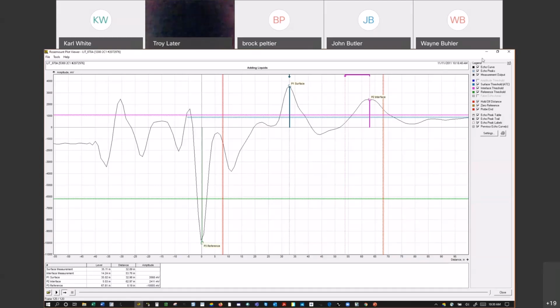Well, yeah, and even just from the operator's description where he says, I've got good interface, and all of a sudden it's just gone. I'm like, okay, well, you're going below the threshold. So before we even started this plot, I went in and lowered the interface threshold so it's down where the blue line is. I said, all right, now let's turn it on and record for 20 minutes while you're doing a transfer, and let's see if we can tell what's going on.